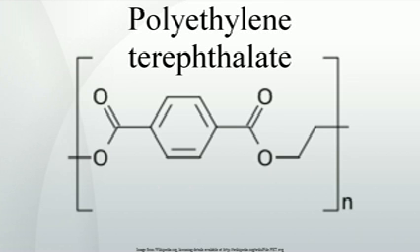Physical properties. PET in its natural state is a colorless, semi-crystalline resin. Based on how it is processed, PET can be semi-rigid to rigid, and it is very lightweight. It makes a good gas and fair moisture barrier, as well as a good barrier to alcohol, requires additional barrier treatment, and solvents. It is strong and impact resistant. PET becomes white when exposed to chloroform and also certain other chemicals such as toluene.